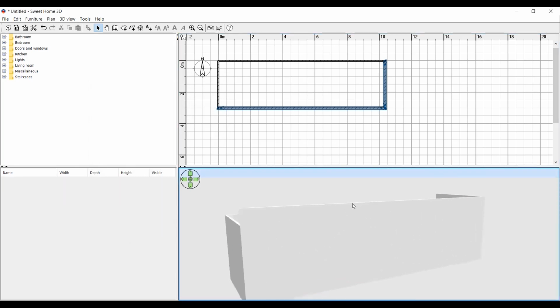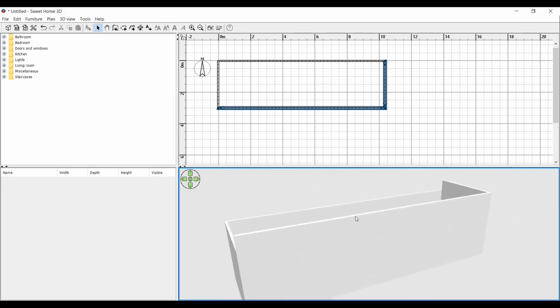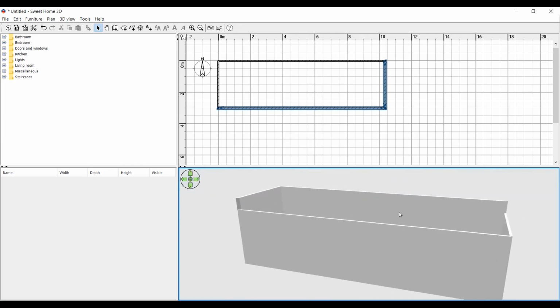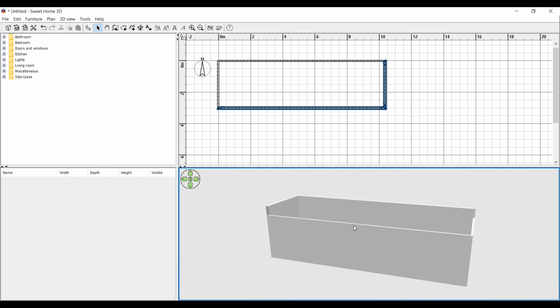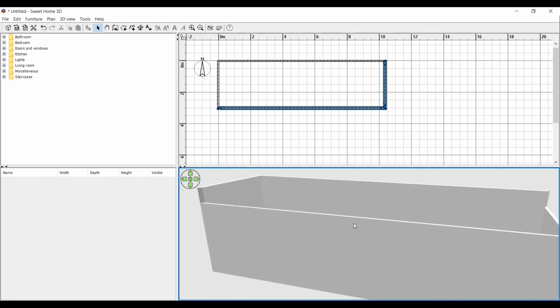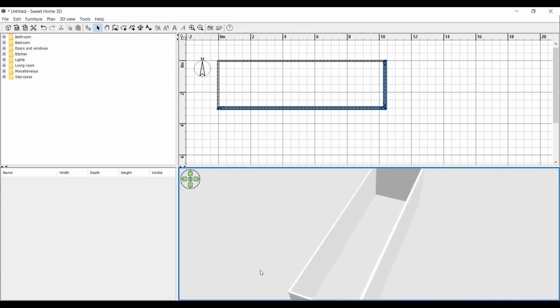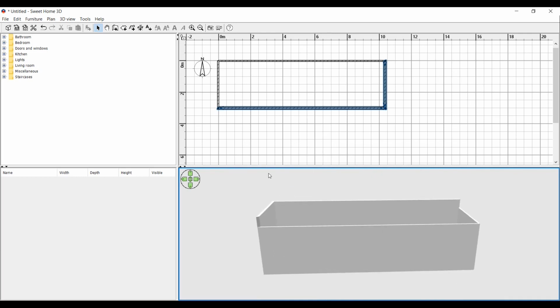Also, for rotating, hold down the left mouse button, then move the mouse. In order to zoom in or zoom out, use the mouse scroll wheel. Hold down the Shift key in order to split up. The wall modifying is complete and you see the difference in wall thickness. Please note that I will teach you the textures in the next sessions.